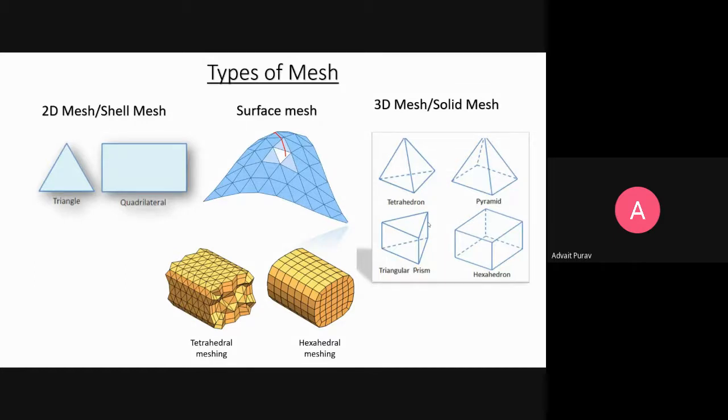There might be holes between two meshes, or cavities, or intersections between the meshes, which we call non-manifold. Non-manifold is a term for when two meshes intersect with each other. So while meshing, defects arise where those two triangular or tetrahedral meshes do not mesh together properly.